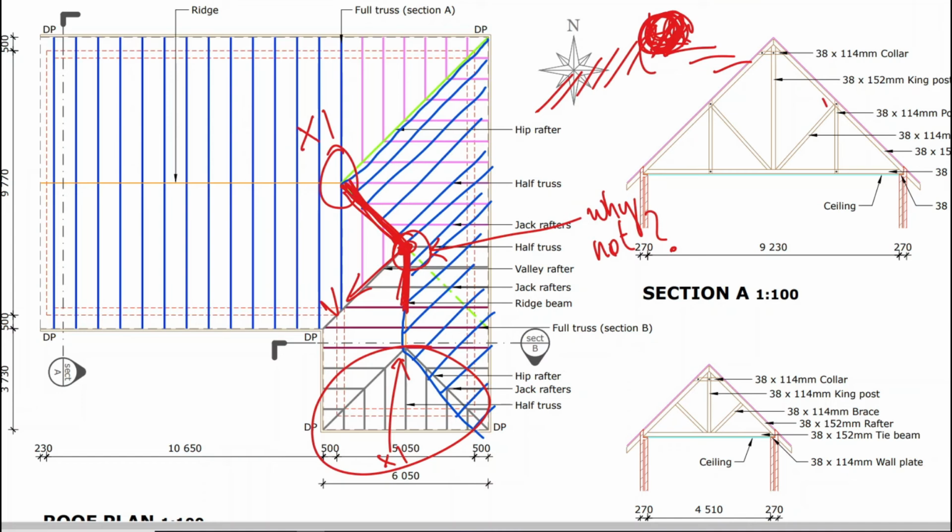But in cases where you have a really intricate ridge coming in, and then it actually splits into two sort of separate hipped ends, hipped ridges, you absolutely are going to need a purpose-made tile there. Okay?